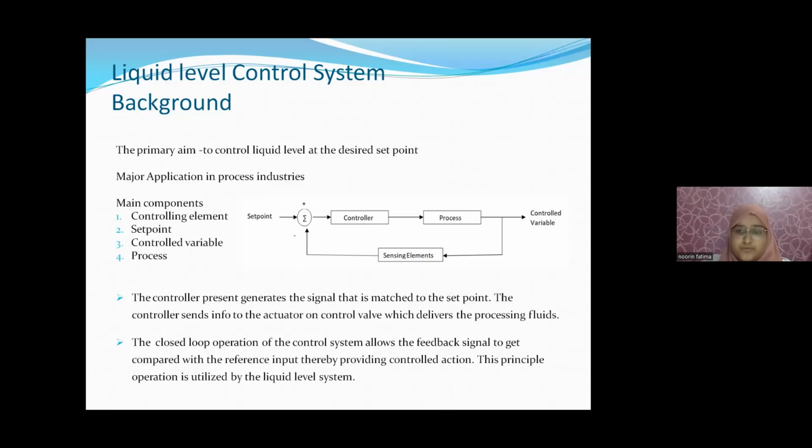There are many controllers which are used. The most common one is PID, generally because of its simple design and structure, and its tuning parameters are set using tuning methods such as Ziegler-Nichols and Cohen-Coon. These are very old, but they are still used because of their ability to give the desired optimum response. But the controllers designed by these parameters give less robust results. Robust meaning they are very sensitive to smaller changes.